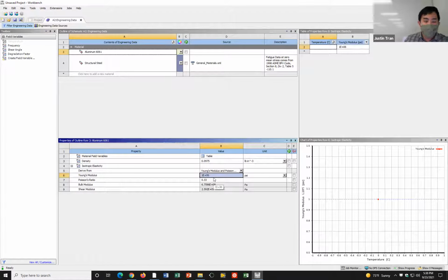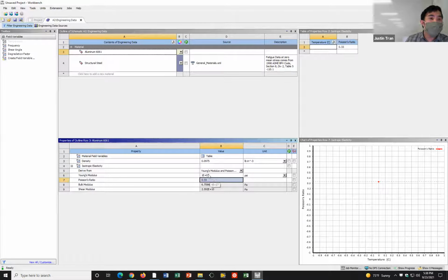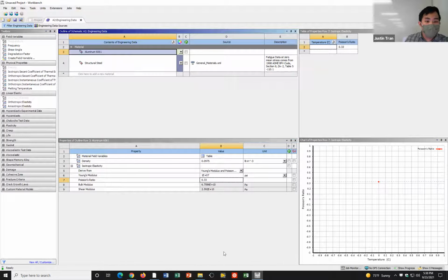But you can. It's just not opening this down here. That's the thing. So I just click on the isotropic elasticity, but because it's deactivated, it's not opening this chart. So this menu down here is missing. Down here. Yeah, exactly. Okay, so you need to reset the view, and so you click on view right here, and you're going to click on reset workspace. Got it. Thanks.